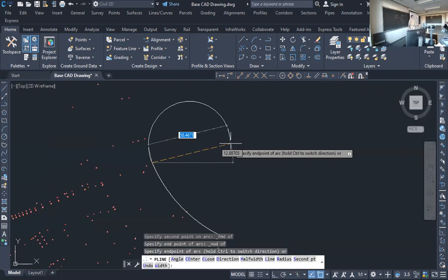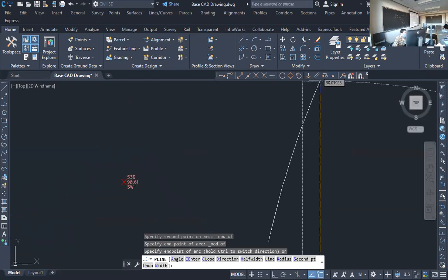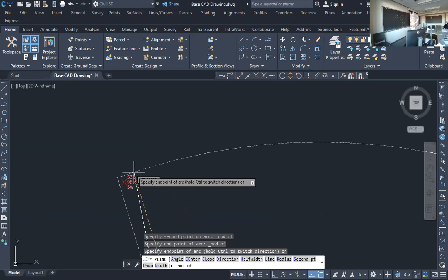Wow, look at that. I'm a draft person. So now, Pearson, what if you were mapping your top curve or bottom curve of the road? Can you select more than 3 points to map? Absolutely. So right now, I'm still in this, right? But you see how the curve's continuing? Now all I have to do is select the next sidewalk point, which is right here. I'm still on a curve, so it remembers the last thing you were doing. So if there's 50 curve points, you just keep selecting your curve points. Did I answer your question? Tyra?